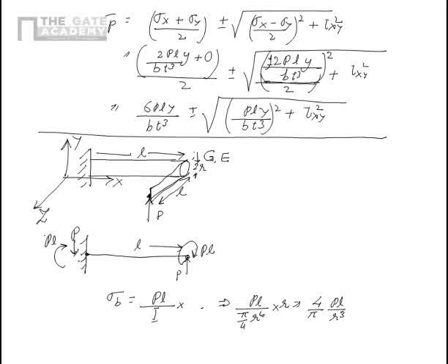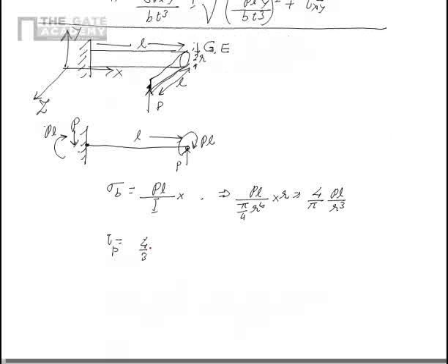Now what is the maximum shear stress, tau? Tau has two portions. One is because of the applied force P directly. The maximum value of that tau is at the center of the bar, which is given by 4 by 3 into P upon pi R square. Please remember that for circular bars or circular beams, the maximum shear stress is 4 by 3 times the average shear stress.